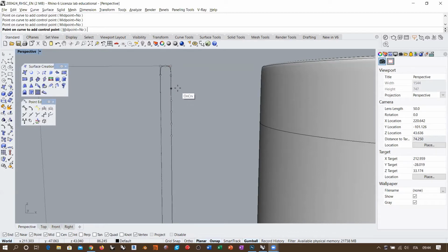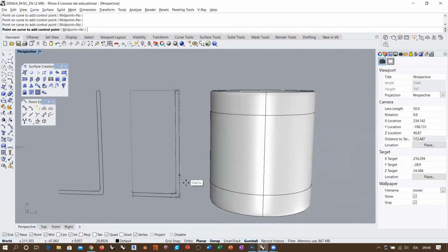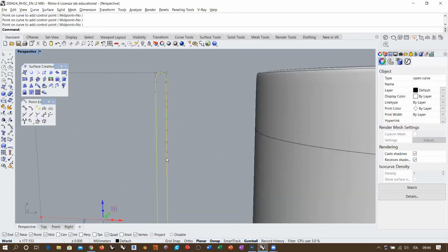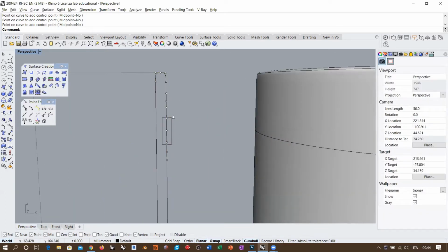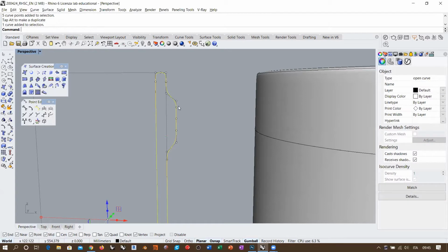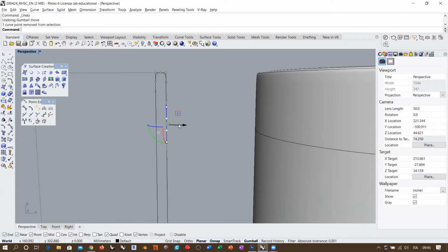So I will place eventually, you see that I have 2 control points here. So I need another couple of control points in order to maintain this side flat. And so I will take, for example, 1 and 2 here. And then I need also 1 here and another 1. Because at the bottom, I already have other 2. Okay? And that's it. Now I will leave these 2 untouched, and I will select these 4 control points, and I can move it away. So I have this flat bulge, and the curve stays flat before reaching, sorry, I think I took too much, yeah, 5. So yeah, these are the 4 that I need.